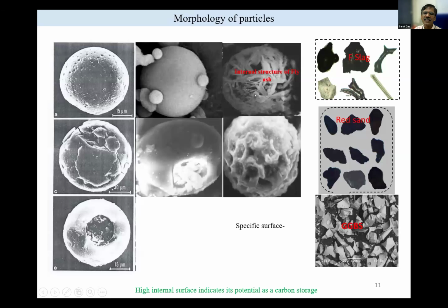These are in the crystal phase and are not reactive with the cement. So this amount will not give you a pozzolanic reaction. In these other fly ash particles, the smooth surface, whatever glassy phase was there, has been used. But whatever remains, some of the iron compound is also there, which will not react.